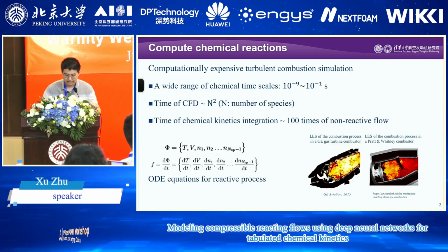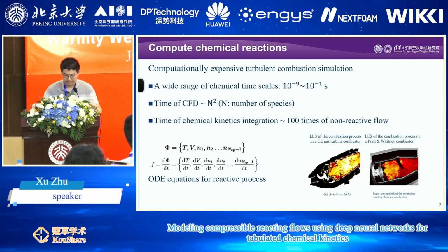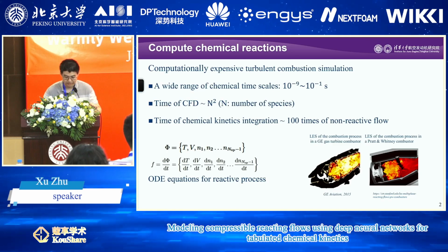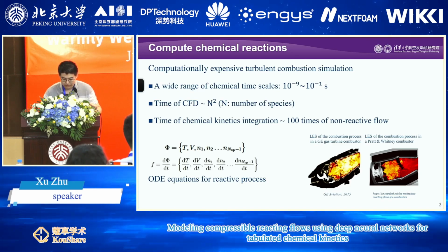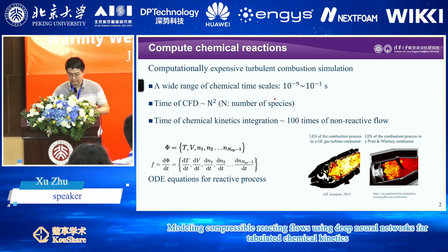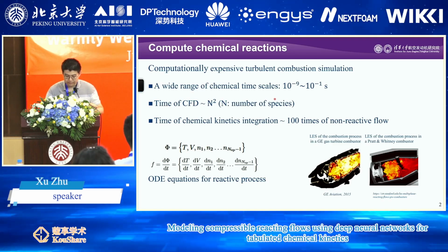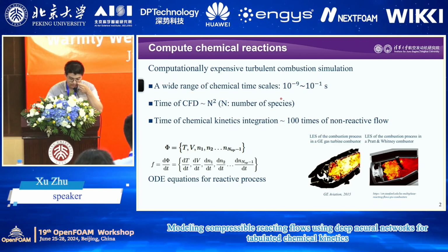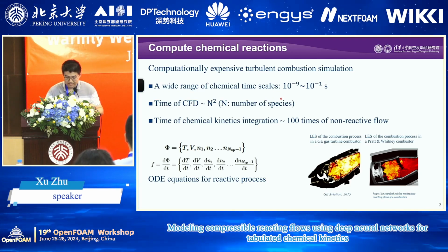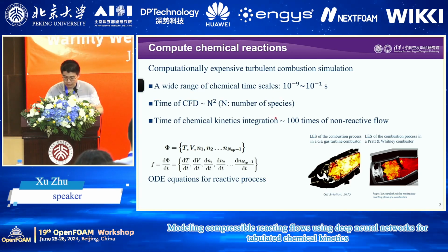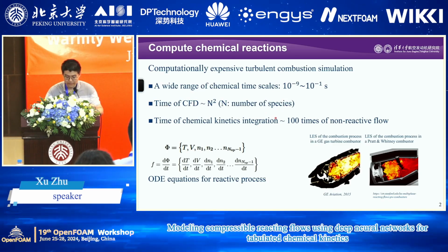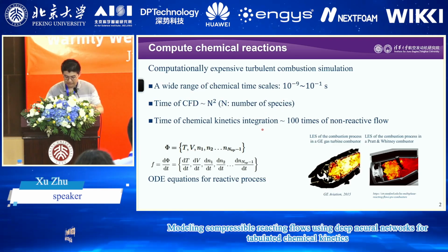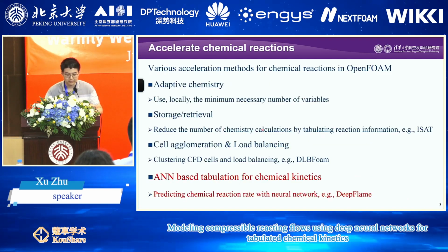So as we all know, simulating turbulent combustion is computationally expensive due to the wide range of chemical timescales involved. And the time required for CFD increases with the square of the number of chemical reactions. This results in the integration of chemical kinetics being 100 times more time consuming than non-reactive flows. So to address these challenges, various acceleration methods have been developed in recent years.